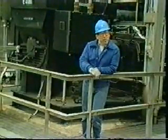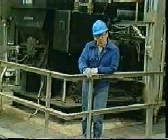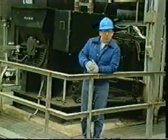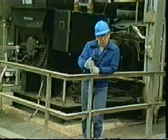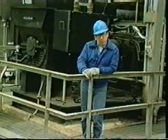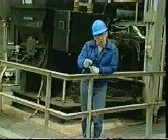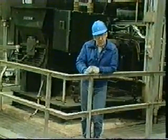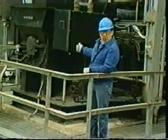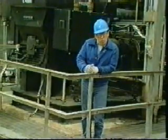Centrifugal compressors are available over a fairly wide range of speeds, anywhere from 3,000 RPM on up to as high as 50,000 RPM. Therefore, the type of power unit used depends on the desired speed range, loading of the compressor, and available fuel sources. In higher speed and load applications, the steam or gas turbine is the most commonly used. Now, in low speed or small load compressors, electric motors are sometimes used. Let's take a closer look at these different drivers.